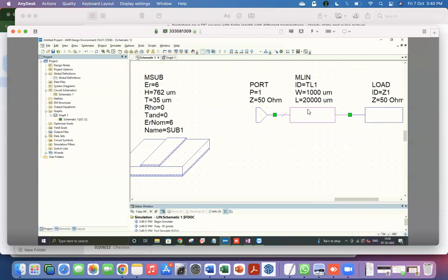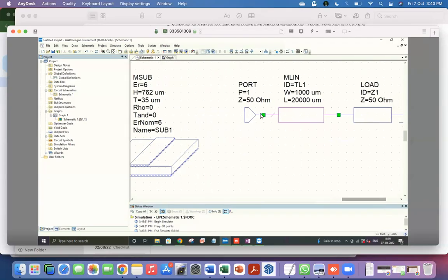We don't know what it is. It's something we want to make 50 ohms, because we don't know the exact dimensions to choose for that right now. It has some length. There is 50 ohm on one end connected, and I'm looking at the reflection coefficient at this point using a port. So I'm looking at the gamma here.